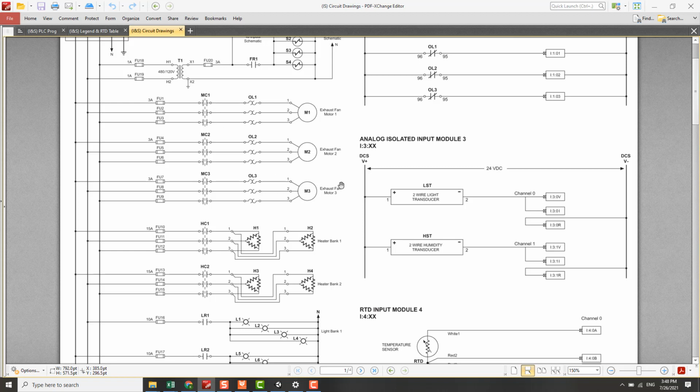Actually, troubleshooting a PLC circuit is not really difficult. In fact, it is very easy. We can always monitor the PLC input and the PLC output LED status. That's all. From there, actually, we can see a lot of the problems. Of course, if you have access to the PLC logic programming, it is even better.